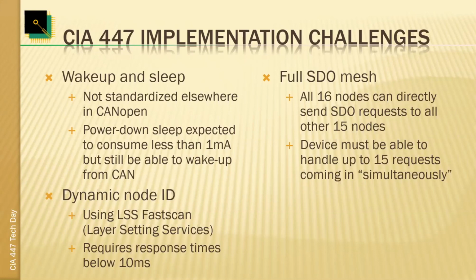And it's not too theoretical, because after a boot up and startup, typically every node starts scanning the network to find their partners. So there'll be a lot of requests. Who are you? Who are you? Who are you? And so your system needs to be able to handle these devices, even if they come in mostly back to back, meaning theoretically they could come in, let's say, within 20 or 30 milliseconds, and then you have to have receive buffers big enough that you can process all of these and really ensure that you reply to each of them.